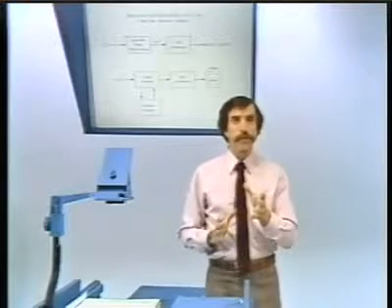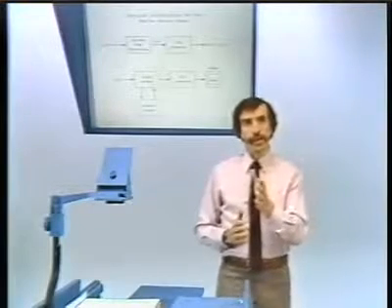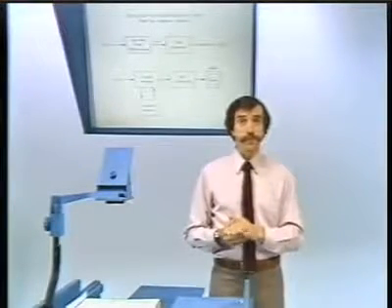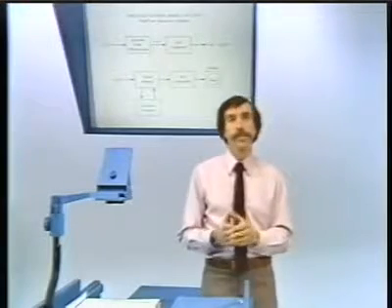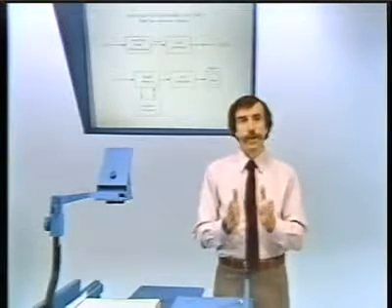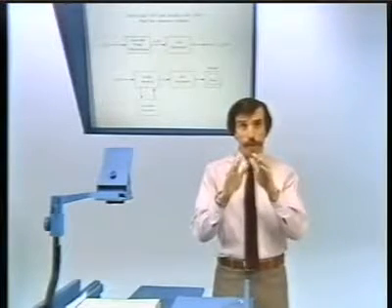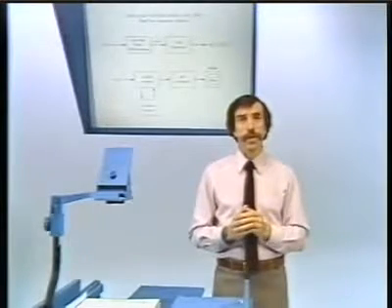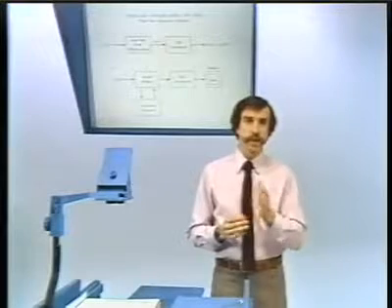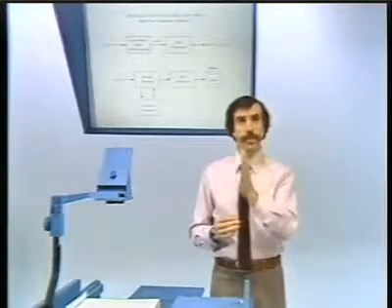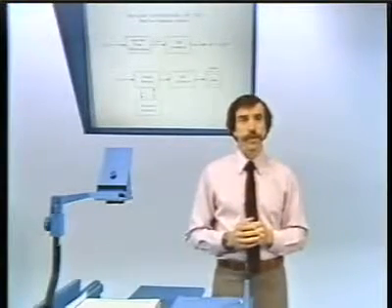So what we're computing, of course, are samples of the Fourier transform. And so, for example, if the input was a rectangular pulse whose Fourier transform is of the form of a sin x over x function, what we would in fact see on the display are samples of that at discrete frequencies.